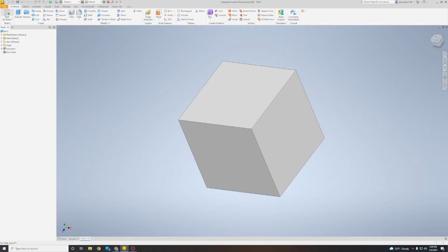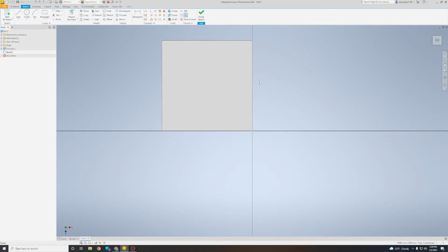Clicking Start 2D Sketch, I'm going to choose the side that I want to make hollow. In this case, I'm looking over at my navigation cube, and I'm seeing top, and I like that. Top is an easy way for me to think, because I want that 6 to land on top. So I'm going to click the side that's labeled top. I'm going to draw a rectangle inside of there.